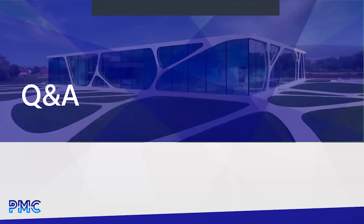Okay. Can you explain what geolocation is? Yeah. So in this context, it's where the point cloud exists within digital space. Typically this is going to be a building column if the columns are exposed. Let's say it's column A1, or it's going to be the southwest corner of the building. What we need to know is the center of that column or the corner of the building, where do you want that to show up in Revit?